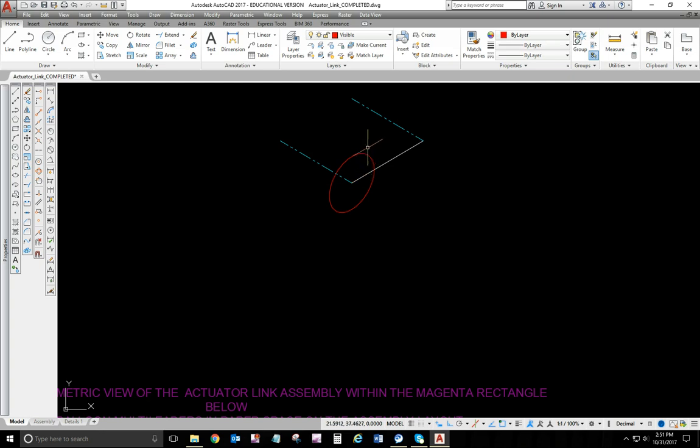Okay. And now I want to copy that back and I have to copy it 3 times because I'm going to need 4 circles as I'm going back. I look at my total depth is 2 inches, and then I've got a 0.75 and a 0.5. So I'm going to copy. I'm going to select that point, and I'm going to toggle my cursor to there. And I'm just going to come back here to the snap just so it'll hold it to there, and I'm going to type in 0.75. Then I'm going to copy it again, the additional 0.5, which is going to be 1.25, and then a third time, which will be the full 2 inches.